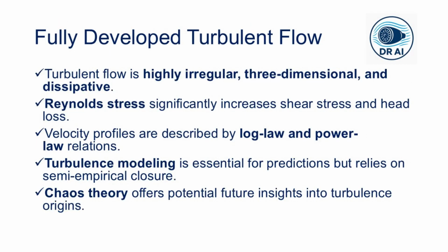Now, let us bring this all together. Today, we stepped into the chaotic world of turbulent flows. We saw that it is characterized by randomness and fluctuations, which we describe using mean and fluctuating components. We learned that the shear stress is dominated by the Reynolds stress, a macroscopic momentum transfer from the tumbling eddies, which is vastly larger than the laminar stress. We also discovered that turbulent flow has a layered structure: a thin, linear viscous sublayer near the wall, a turbulent outer layer, and a logarithmic overlap layer connecting them.